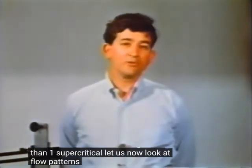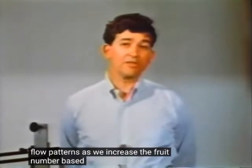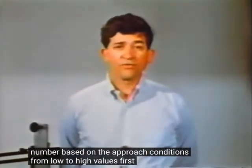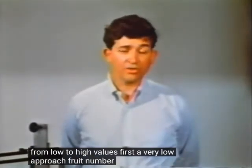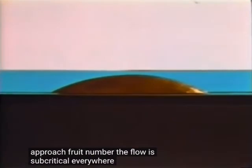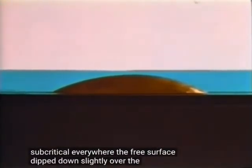Let us now look at flow patterns as we increase the Froude number based on the approach conditions from low to high values. First, a very low approach Froude number. The flow is subcritical everywhere. The free surface dips down slightly over the obstacle.